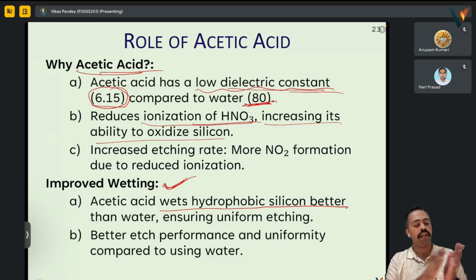also we see that whole oxide is removed. And how we understand that whole oxide is removed, you dip into DI and take it out. If there is some water sticking over the surface, that means still some oxide is left. And once the whole oxide is removed, if you dip into DI, nothing will be there on the wafer. Everything, all the water will get repelled because silicon is highly hydrophobic.